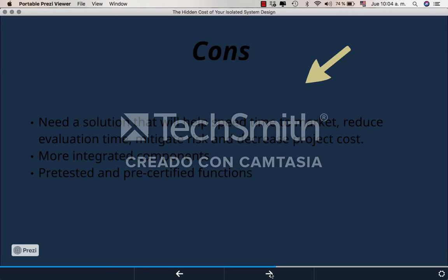Cons. While insulation is an essential part of the design, it's far from simple. From determining the required insulation level, to providing insulated power to complement the insulated data path, to making the solution fit the available space, many design trade-offs must be evaluated.